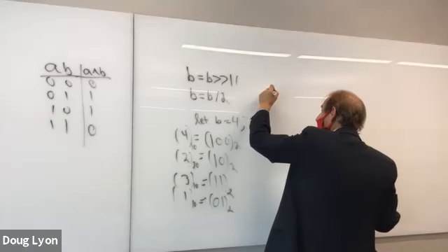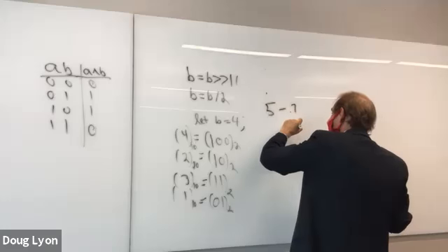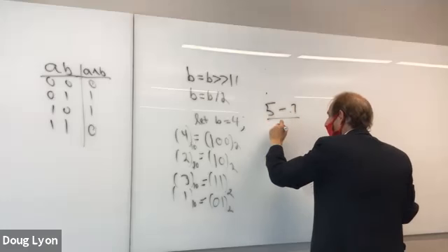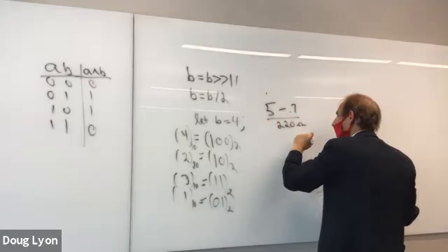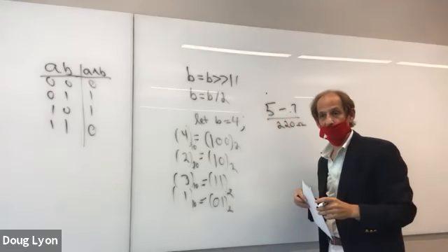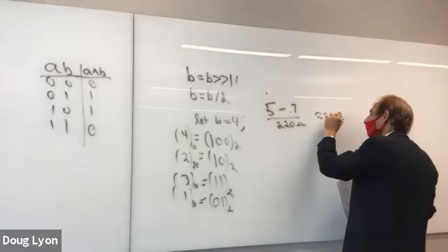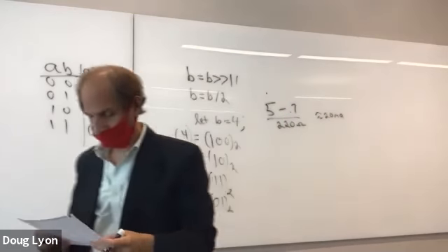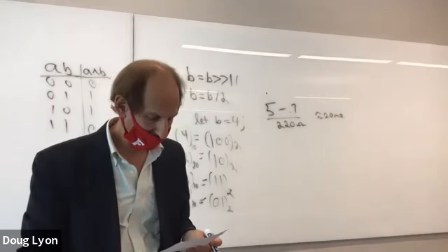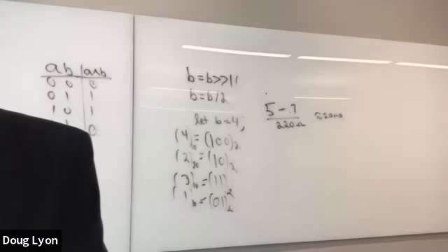But if you've already done it, I can't really correct it. So anyway, it's 5 minus the voltage drop, which is probably 4.3, divided by 220 ohms. 19.5 milliamps. What kind of number did you get? 19.5. 19 and a half milliamps. Can we call it 20 milliamps? Twice as much. Yeah, well, it says 9 milliamps here. Yeah, this is a bug. I've got a bug in my answer key.